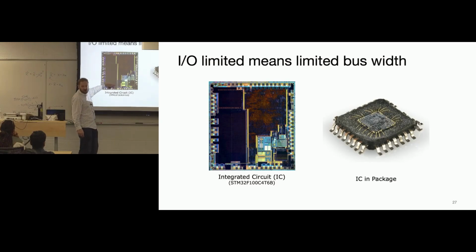So you could use it for GPIO, you could use it for an analog function, you could use it for PWM, you could use it for all these things, and that is what your control register on your device was doing, right? You were selecting which functionality goes to this pin. So basically you're doing a multiplexer. You still only get one signal out at a time. So you'd have to do time domain multiplexing between those things.